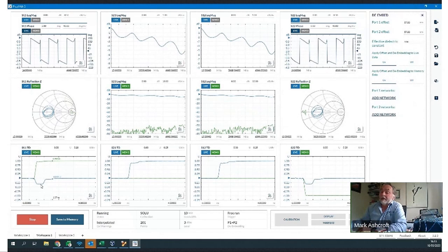And notice that when I am fully de-embedded, there's a cursor reading there. Wherever I hover on this trace, I get cursor readings wherever I go. And if I come to this point here, that is reading off as very nearly 0 nanoseconds at the bottom of the plot in black. That's because I've de-embedded what was a short and de-embedded the DUT line impedance here.